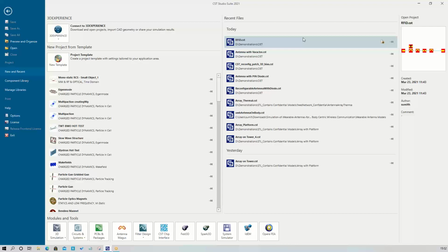So what they are looking for is the envelope pattern. The envelope pattern is all the beams which are scanning combined together. Because the switching is fast, you will not feel like there are separate beams. You will see a single beam only, which has wide coverage. So instead of placing one omnidirectional antenna, they are using a huge antenna array, each antenna having a very sharp beam, but scanning in a fast mode left to right, right to left, and up and down.